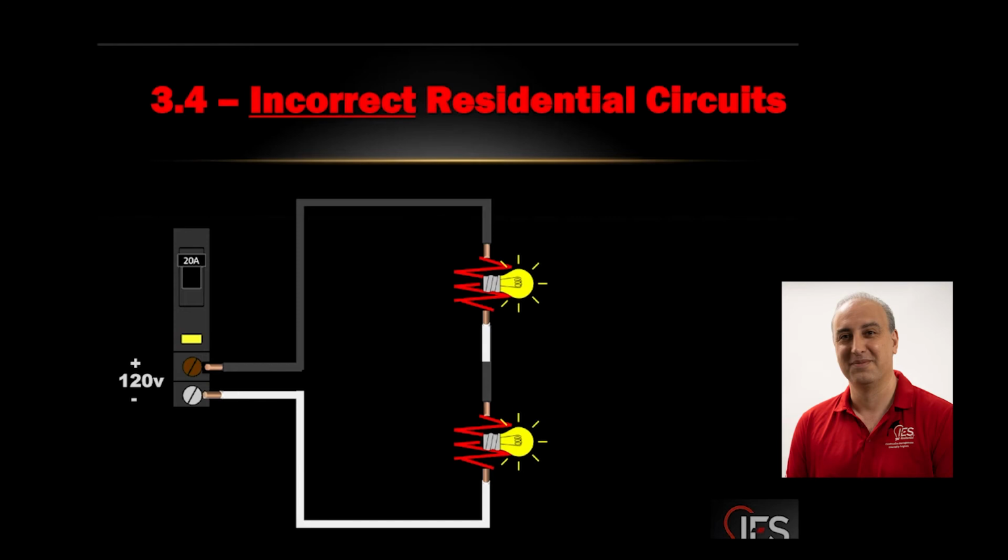What happens here, the same current flows through both of them. But look at what happens to the voltage. You're splitting the voltage between those pieces of equipment. So if they're exact same light bulbs, they each get half of your voltage. If you have a 40 watt and 100 watt, they get different level voltages, depending on resistance. The higher resistance gets the highest voltage.